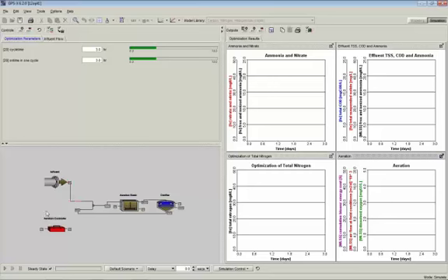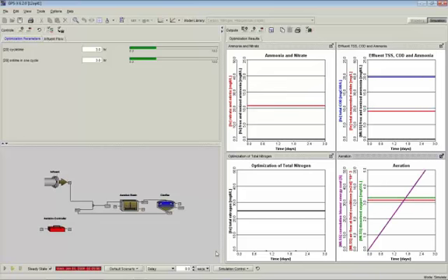So this is complete full aeration all the time. The ammonia coming into this plant, by the way, is about 24 or 25, I think. So when I run this simulation, we can see from this graph that we're getting pretty much full nitrification for the SRT that we're running at. We're generating nitrate. And here's our total nitrogen that's coming out of the plant. It looks like it's about 24.7. So remember that number in your head, 24.7. That's what the situation is like if you aerate all the time.